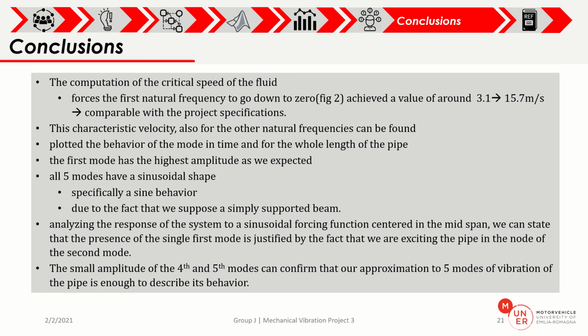All modes have a sinusoidal shape due to the fact that we suppose a simply supported beam. We also confirm that 5 degrees of freedom are enough to describe the system, due to the small amplitude of the 4th and the 5th modes, and that the presence of the single force mode in the response of the system is justified by the fact that we are exciting the pipe in the node of the second mode.